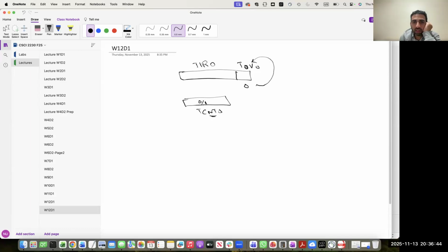On every upcoming clock, the value of the TCNT0 register is incremented. So it checked when the value is 0: no overflow flag. Then the value is incremented to 1. Is the overflow flag set? No. At 2, is the overflow flag set or not? No. And we continue. Finally, when we reach 255 and on the next clock it changes from 255 to 0, then this flag is set.